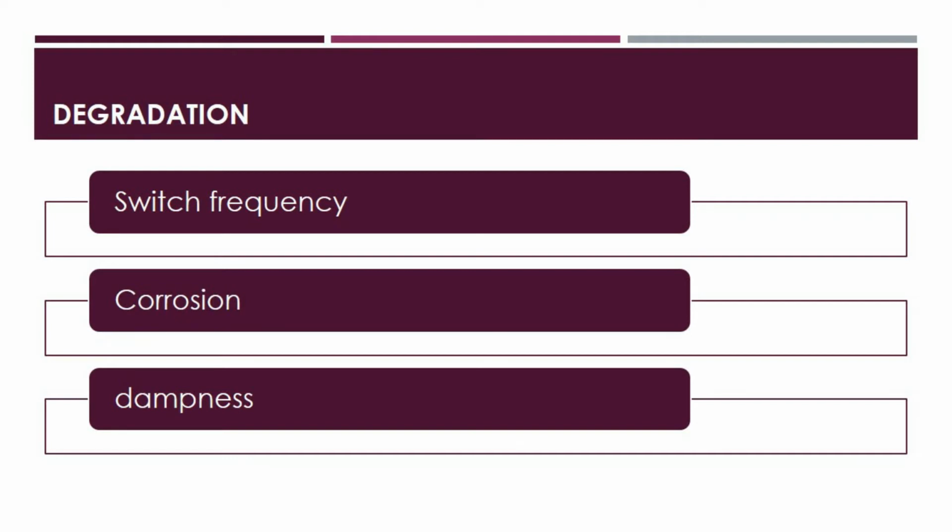The life expectancy of switches in enclosed switchgear is influenced by a variety of factors. The frequency of switching operations, the load, the presence or absence of a corrosive environment, and the presence or absence of dampness or moisture at the installation location are all aspects to consider. The switchgear can have a service life of 30 to 35 years on average, provided it is properly maintained.